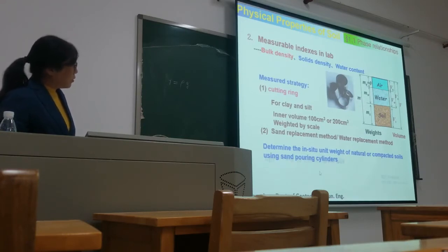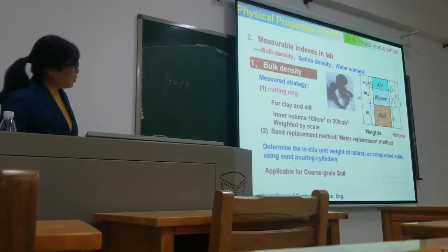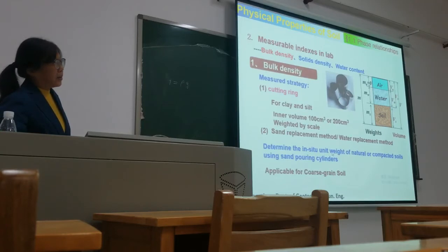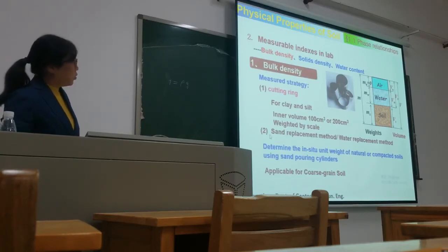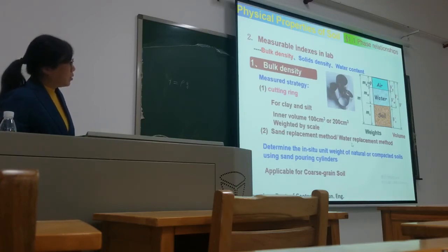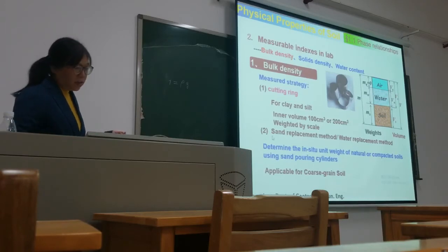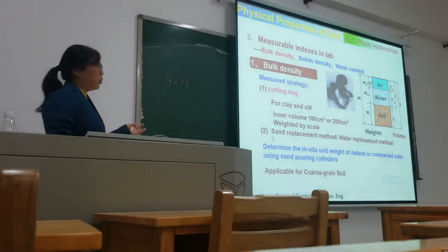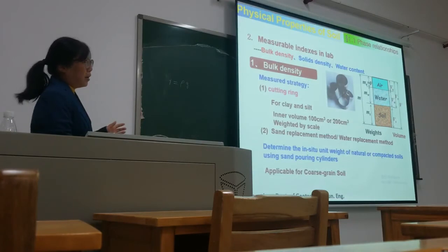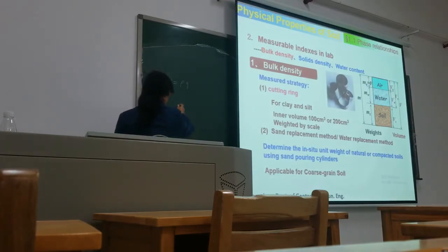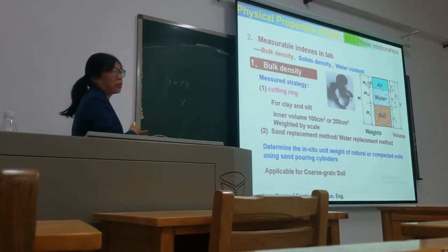But for in situ tests, we should use the sand replacement method or water replacement method. Here, sand replacement or water replacement aims to get the volume of soil.